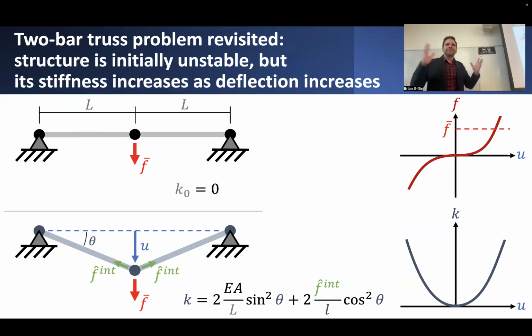So how do we characterize the stiffness associated with this single displacement component? Let's focus on defining stiffness as just the transverse stiffness associated with the transverse motion of this node. And let's also determine the resulting transverse resisting force associated with that kind of transverse motion. In the case of small deformations and small strains, there was no stiffness associated with this initial configuration of the member. So there was nothing to resist this node from shooting off to infinity and beyond.